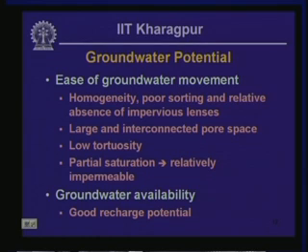Then the second point to consider while considering groundwater potential of a deposit is that the formation preferably should have large interconnected pore space. Low tortuosity, that means the interconnected pore space should be aligned without much deviation from a straight line. Then partial saturation actually makes a soil relatively impervious, because of capillary tension that develops within the pore space of such deposits.